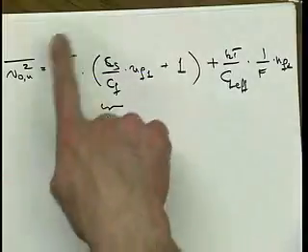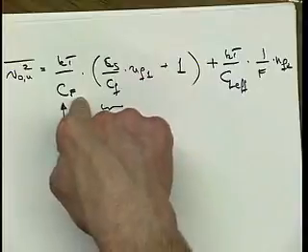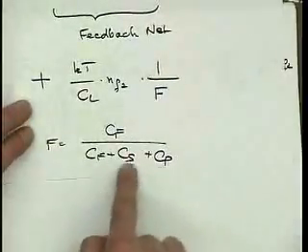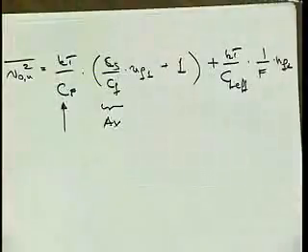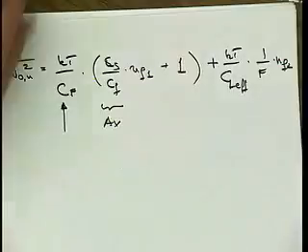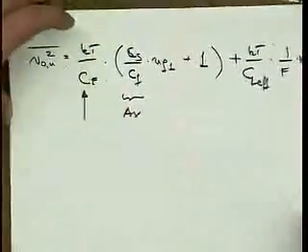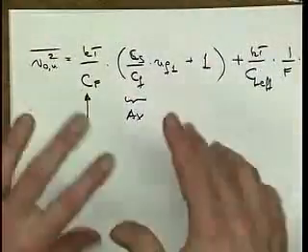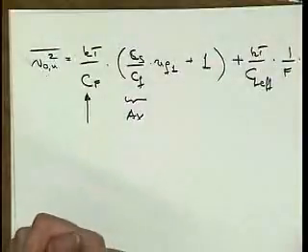Of course, there is also stability and the feedback factor F that are affected by choosing CF. We've also said that CF shouldn't be a lot smaller than CS and CP, right? So now we have yet another consideration when we determine what we are going to use as our feedback network. I say that because I've seen solutions where CF, a bad thing, adds load and area and so on, so why don't we make it almost zero? Well, no, please not.